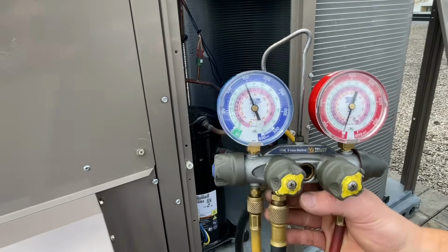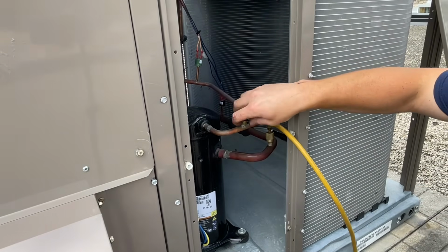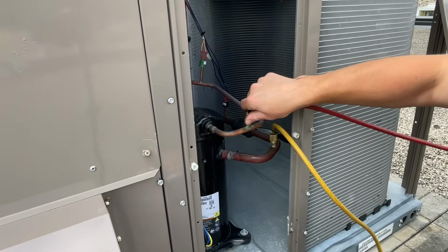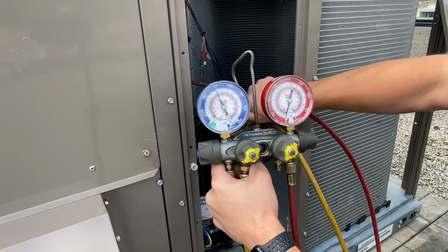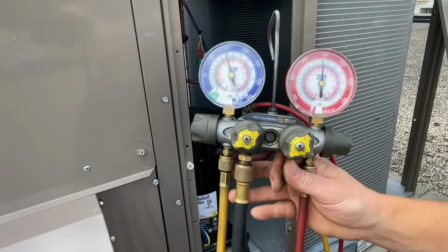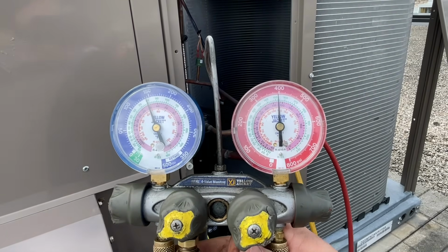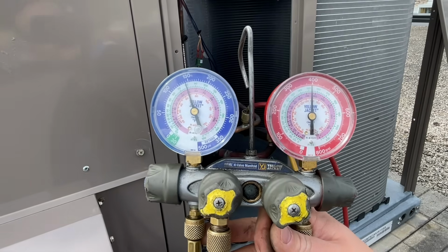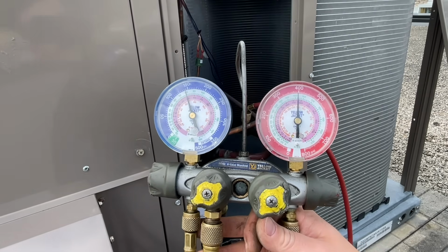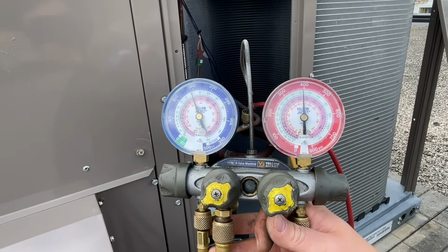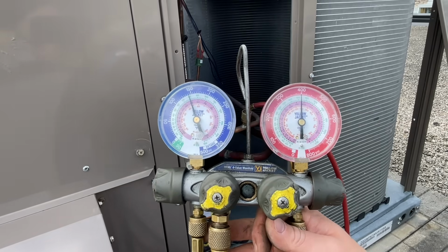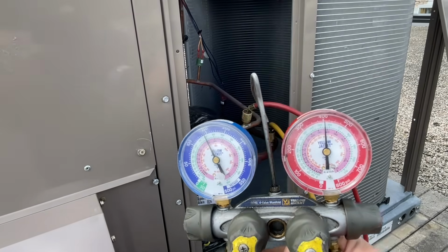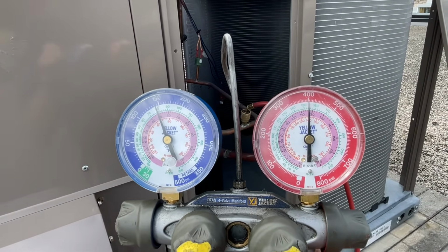Let's check our head pressure quick. She's up there, 400, a little bit high, but I also have this panel door off right now, so we're sort of bypassing the coil. But yeah, this unit's doing everything it can to try and compensate for the other bigger one down. Okay, so now that we know this unit's running fine, we're gonna run over to the supplier and see if we can pick up that motor. Well, first we gotta clear it with the customer, but stay tuned.